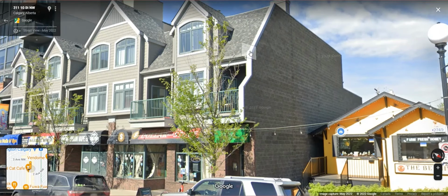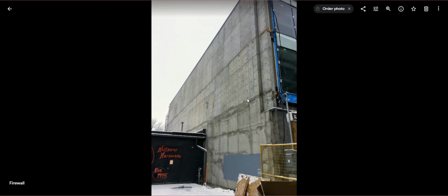door. So I'd say those are two of the primary reasons, and a third and fourth would be why you still need a non-combustible wall. So the masonry is non-combustible, and you still need a fire rating on that wall based on the spatial separation. So you're getting the fire resistance rating with the concrete block as well. And so as I mentioned earlier, they don't have to be concrete blocks.